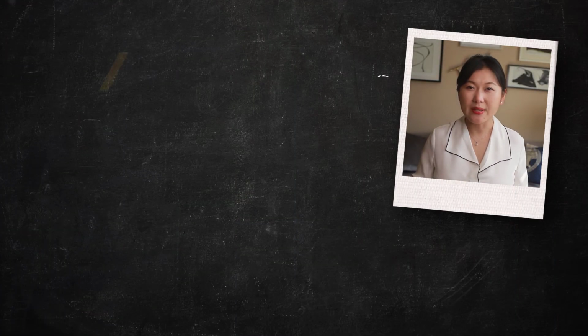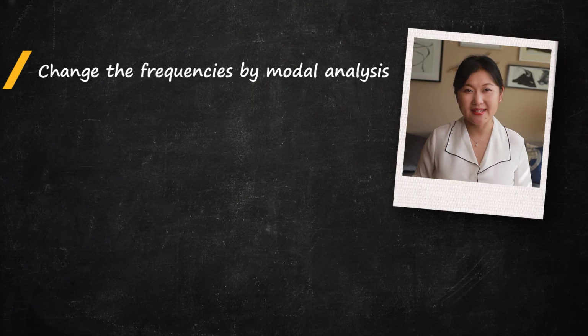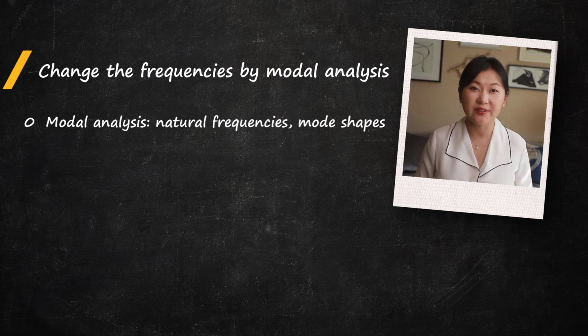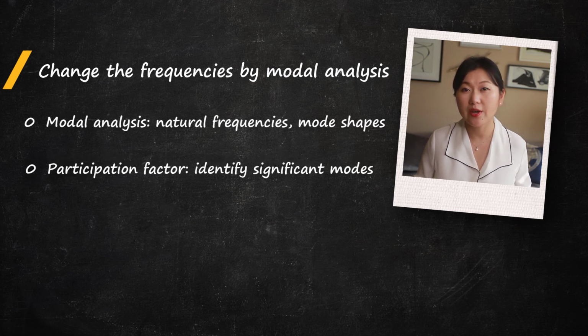In summary, we now know the importance of the modal analysis. It is a very useful approach to determine the vibration characteristics, the natural frequencies, and mode shapes of the structure. Once we extract the modes of the structure under free vibration, the participation factors can be instrumental to help us identify the significant modes that we need to focus on.